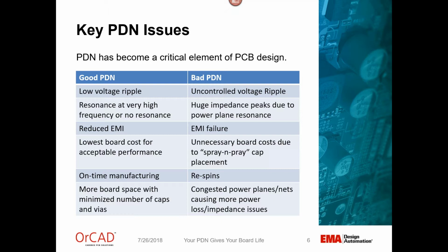capacitor placement method. So we can approach this both on the board design side and make improvements for our manufacturing side by avoiding respins and giving us more board space to work with by minimizing the amount of capacitors and vias we put down.